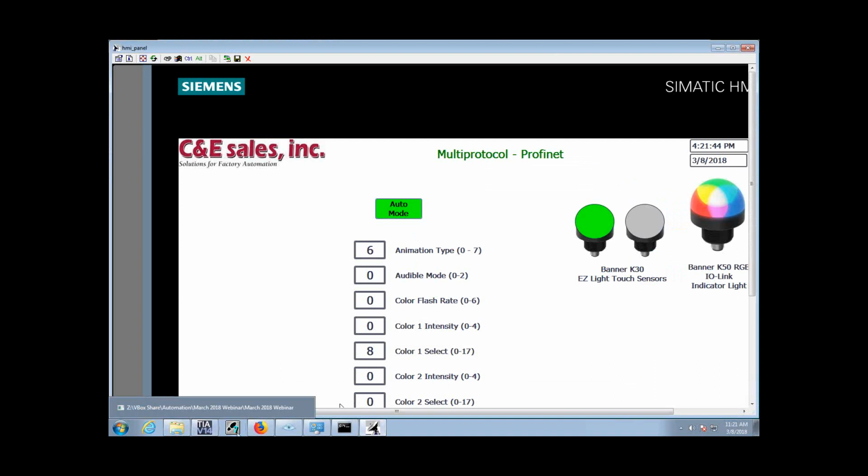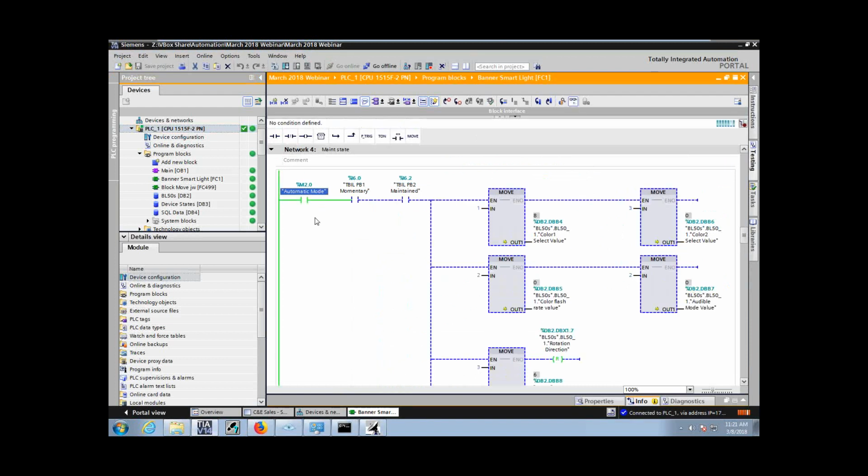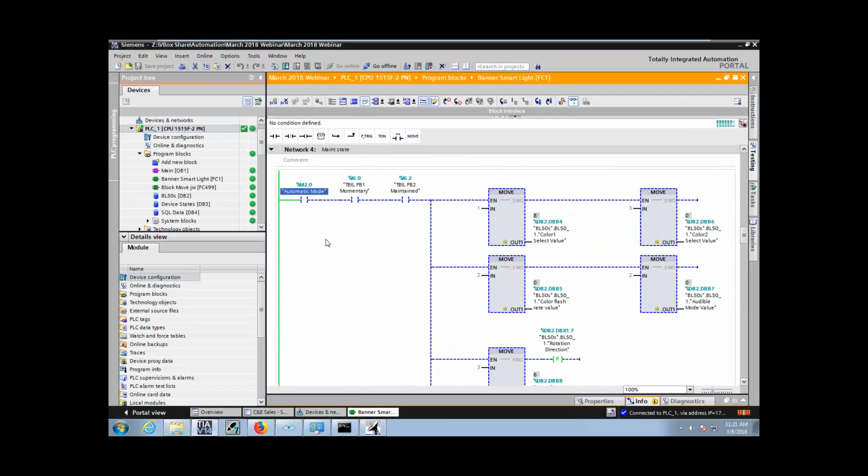So now I'll be back online with the PLC. I'm already online with the HMI, and I can ping none of these devices now. So here we go, I'm in automatic mode. Put it in manual mode, and there you can see my state changed. So we're connected through NAT, through the S615, and we're also firewalled.